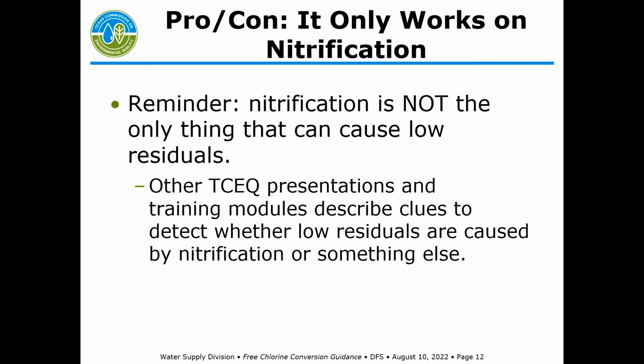So this is both a pro and a con. The free chlorine conversion only works if the problem is nitrification. And we've already mentioned, there's other things that can cause low residuals. I'm not going to really talk about those in any detail today. There are other TCEQ presentations that'll give you tips on how to determine: is the problem a treatment failure?